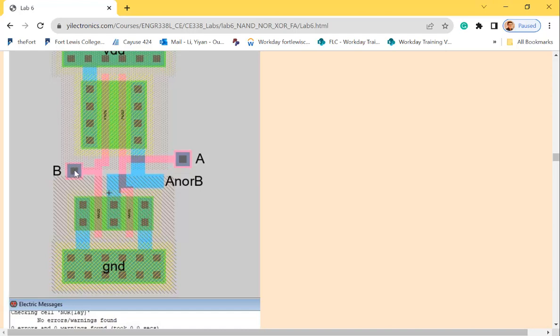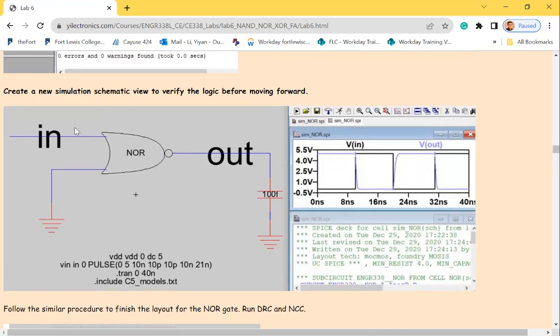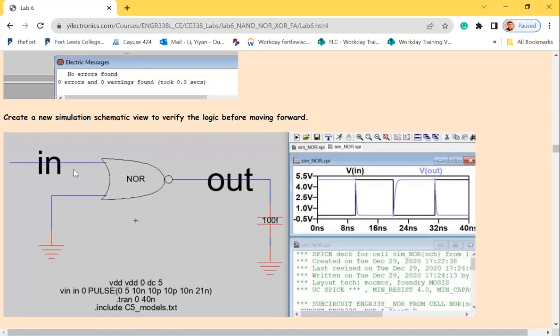And why do I have to put a via on poly immediately, or just keep it in here instead of make a via somewhere else, then contact to metal one? Because you do need, so these are the input and output of the gates, like these ones. I think this NOR gate has 2 inputs, one here, and this is the output. It's actually this one, and output.